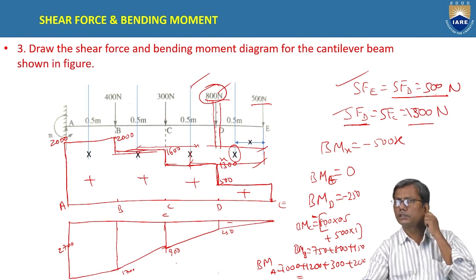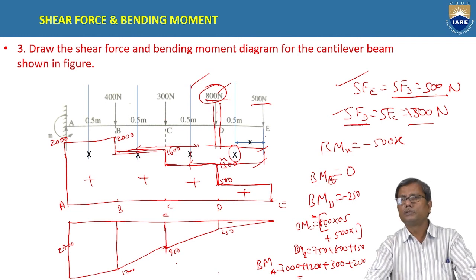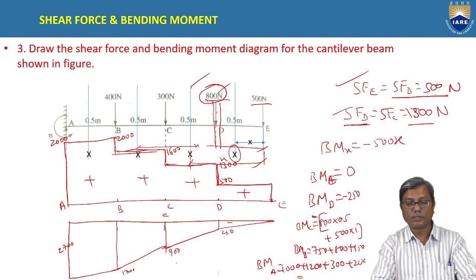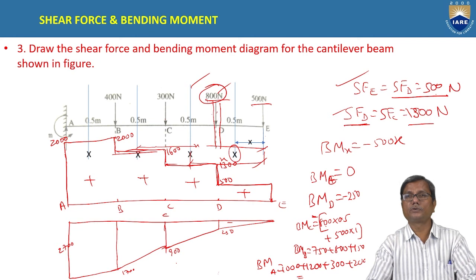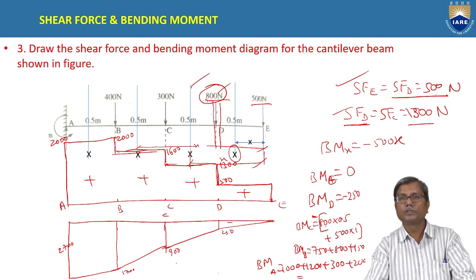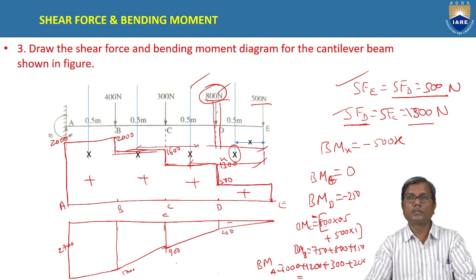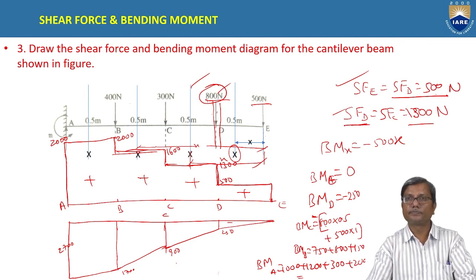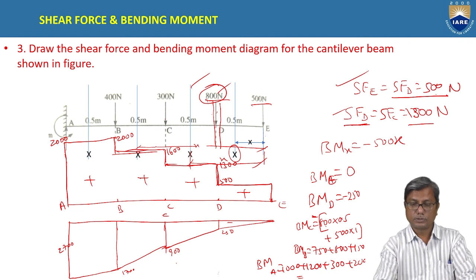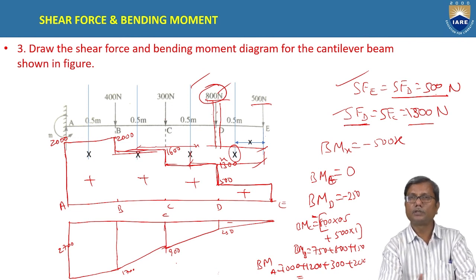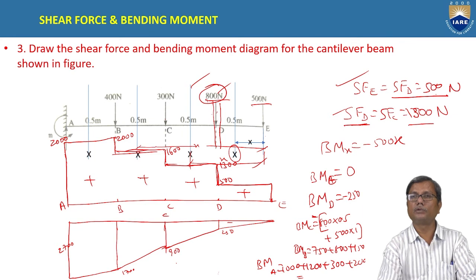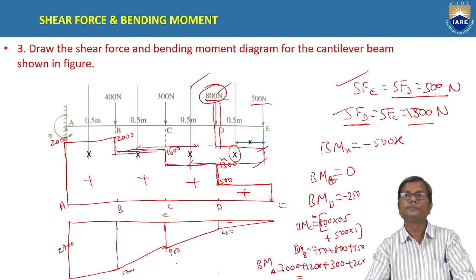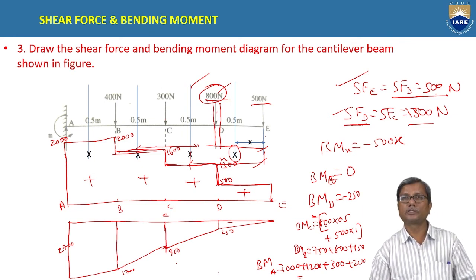Okay. It consists of triangles and trapeziums. Triangles and trapeziums. Okay. So like this, when there is a series of loads, point loads are acting, we can easily draw the shear force and bending moment diagrams. Okay. Just shear force is obtained just by summing up all the forces. Similarly, the bending moment also. Okay. Yeah. With this, we end this session.